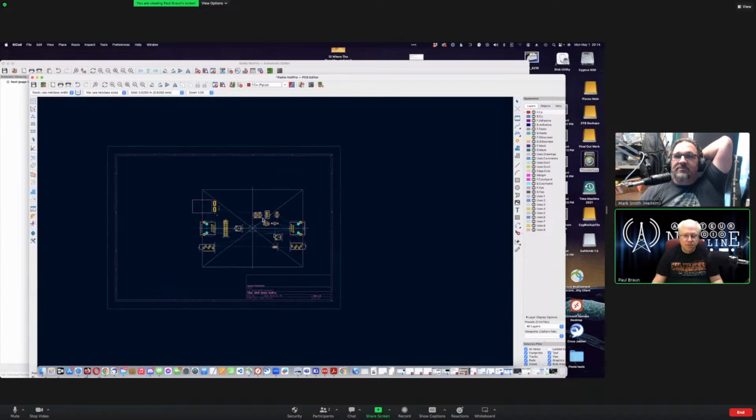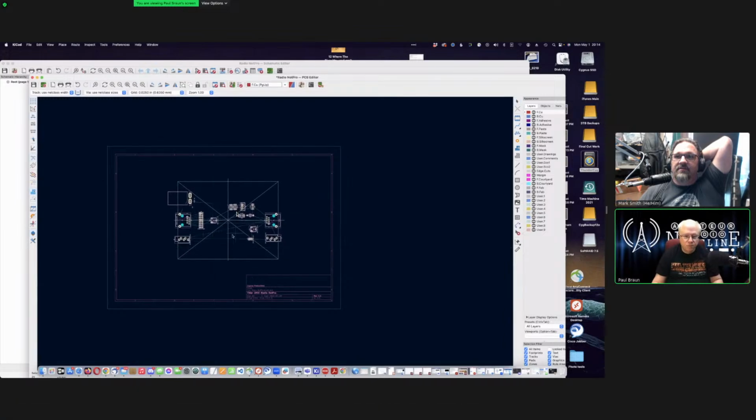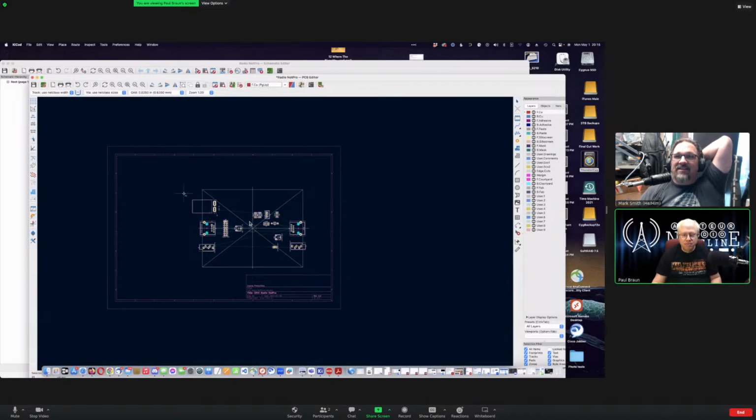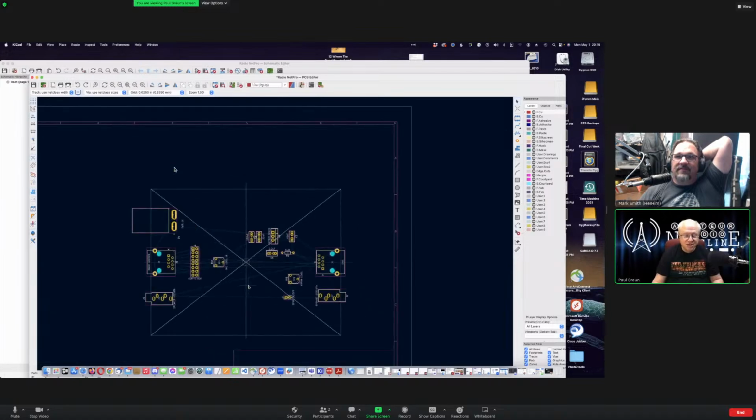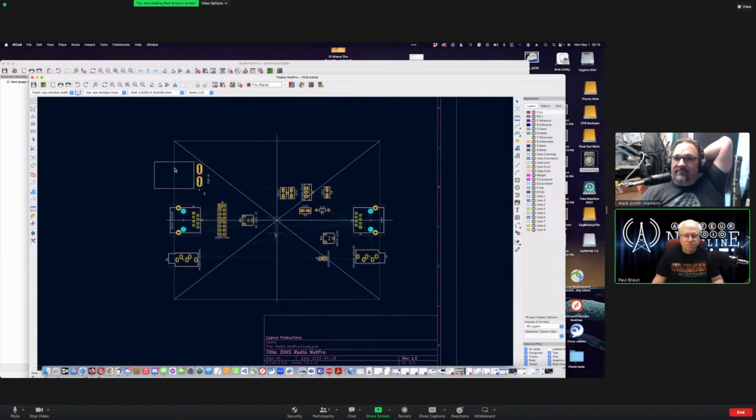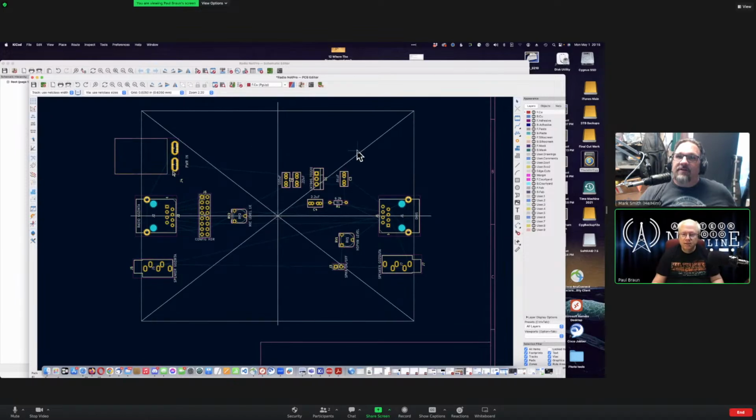I would move the power supply components closer to the RJ or to the Anderson. Hold on. Don't move anything yet. Oh, shoot. That's fine. I messed up the origin. You can move it. It just means you need to replace the origin. That's all. I put it back. We're okay. I was just trying to make it a little prettier. This doesn't matter. Okay, so move the power supply stuff up in here. I would move the power supply stuff closer to the Anderson power pole, yeah.